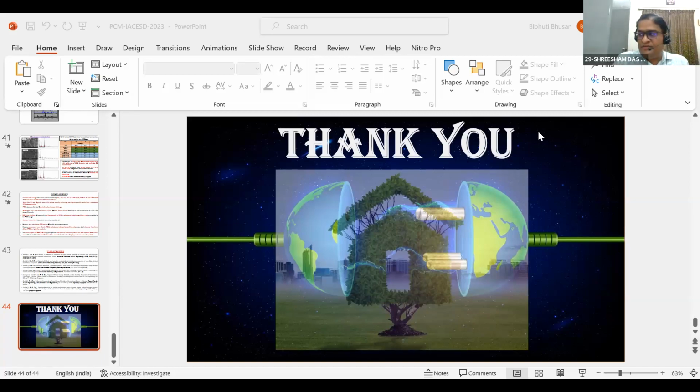If you avoid the curing, definitely you will have sufficient formation of micro cracks, and those micro cracks will later lead to durability issues. So the material that you have designed for 50 years or maybe 100 years will last only 20 or 25 years.